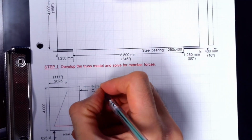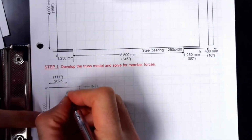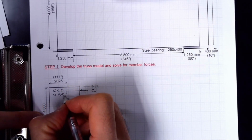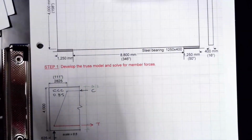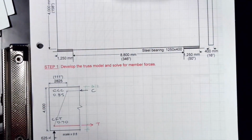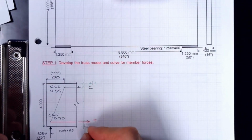Stress block approach, call this A over 2. Again, remember the multipliers. The node at the top is CCC. CCC type of node has 0.85 multiplier. The node at the bottom is CCT. It has 0.7 multiplier. So in other words, this is more critical. It's going to need more space, larger space. The space needs to be larger than A over 2.